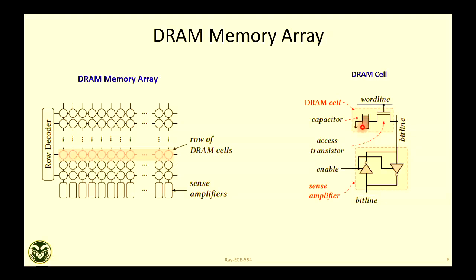These are a few things you need to keep in mind. I'm recalling it because when you do computation, we should not destroy our operands, right? Because we have operands stored in the memory. We'll do the computation, we'll transfer the results, but the operands should not be destroyed. So that's another important criterion that you need to keep in mind: how to do computation without destroying the data. And first of all, let's ask how we'll do this computation using this machinery, because we are not changing the hardware. Suppose I have a commodity DRAM array. How can I do computation inside this array without changing the hardware?